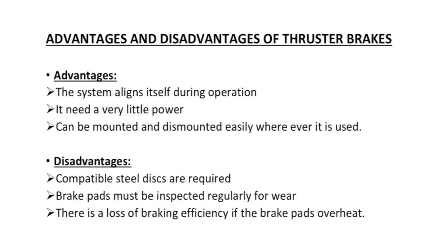Then the disadvantages: compatible steel discs are required. Brake pads must be inspected regularly for wear, and there is a loss of braking efficiency if the brake pads overheat. So these are the advantages and disadvantages of brakes.